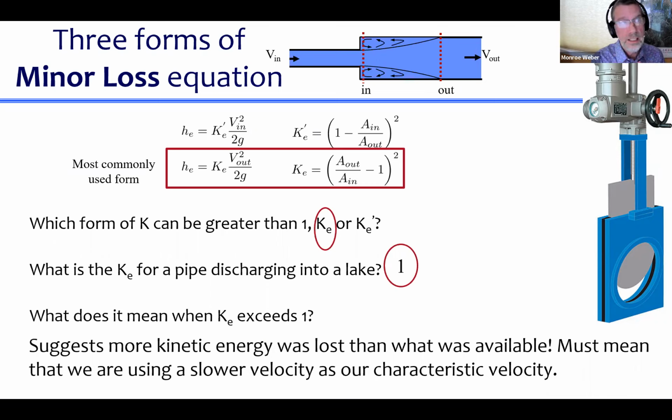So that means that your K value is based on this velocity of the flow through the entire pipe, but it is possible to close that gate valve down a whole lot. And that means that the velocity in the pipe can be tiny compared with the velocity squirting through the opening in the gate valve. Yes?